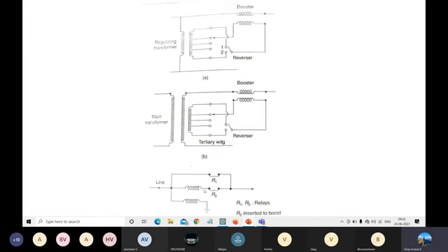This is the normal placing of our transformer windings, the primary side of the booster transformer windings along the line. So this R1 and R2 are different relays which act like switches. If you are interested to use the booster transformer along the line, then close R2 and open R1. After a certain duration, when the booster transformer is not required in our circuit, at that time you can open R2 and close R1. So this will be automatic. Relays work automatically. Okay.